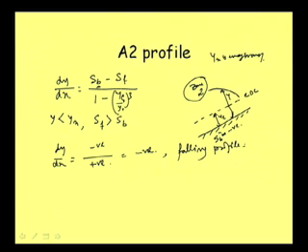And the denominator part is positive, which we can see from the Froude number point of view also: 1 minus Froude number square, and because it is in the subcritical portion, the Froude number is less than 1. So less than 1 squared is again less than 1, so 1 minus Froude number square becomes positive. So any of these forms we can use. Now, dy dx is negative, it is a falling profile.